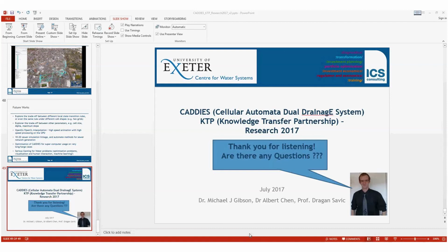That was very interesting. I didn't quite have the time to catch the time step condition. It was one of the earlier pages, but I wasn't quite clear if the time step condition is checked as a local rule or as a global rule. So that is checked as a global rule because you need to have the same time step across the grid.